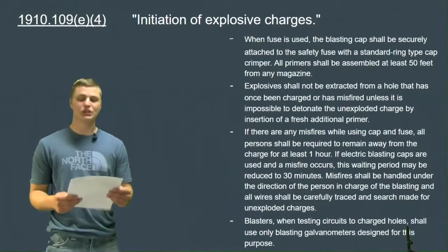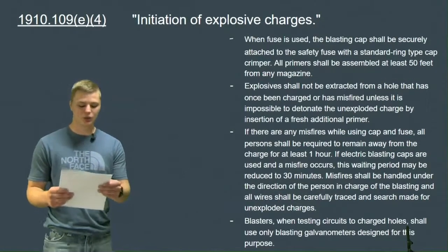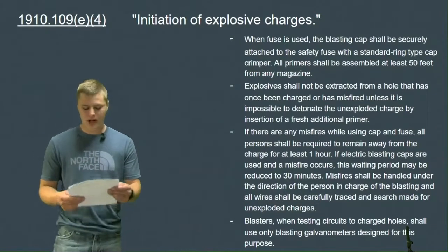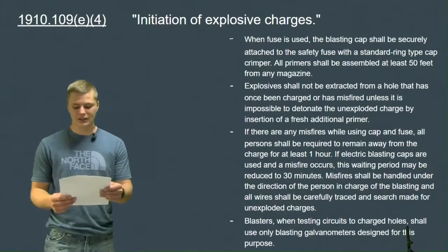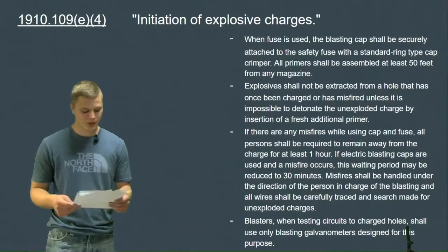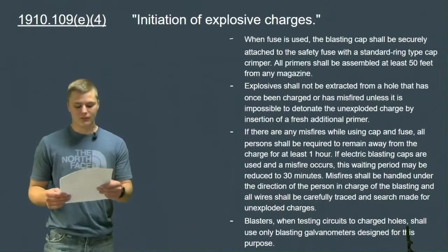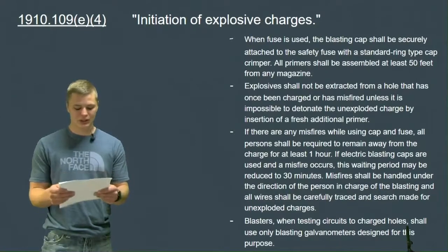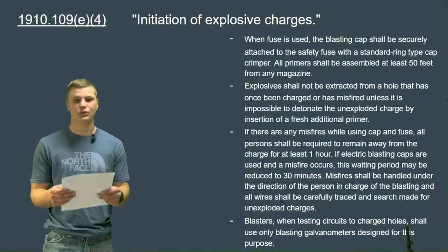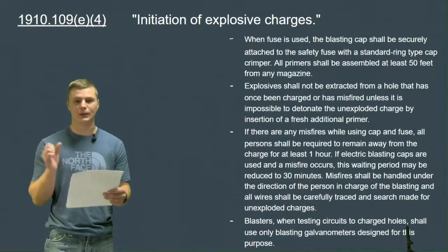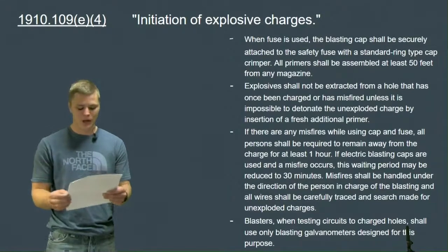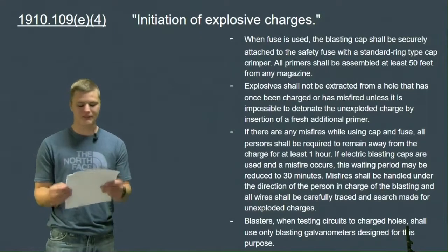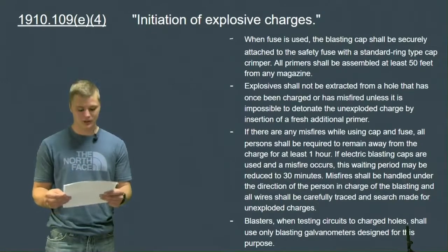When we are ready to initiate the charges, there are rules we must follow, and there is protocol in place in case of a misfire. When fuse is used, the blasting cap shall be securely attached to the safety fuse with a standard ring-type cap crimp. All primers shall be assembled at least 50 feet from any magazine.